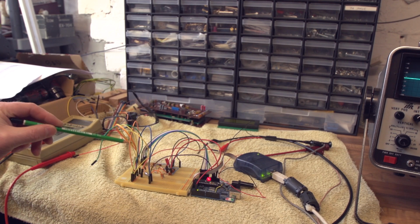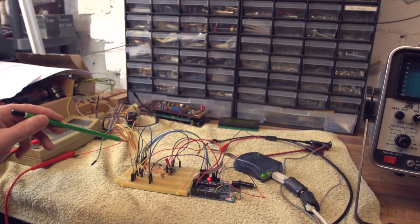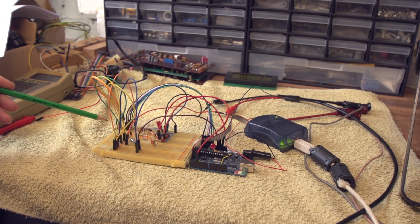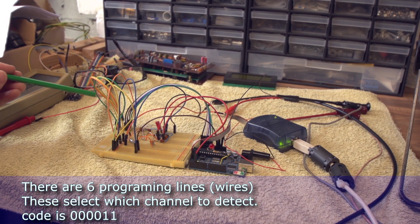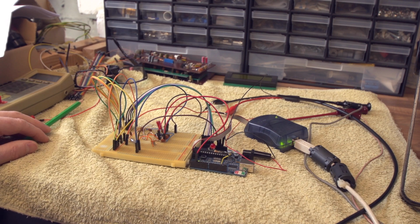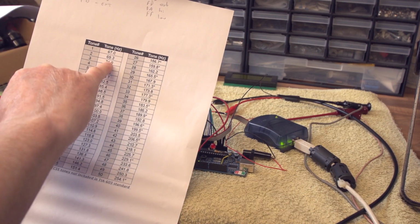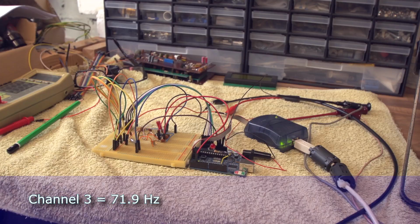I'll change the detection frequency, by changing the binary code, and I'll be back in just a second to do that. Okay, so just like magic, I've changed the binary code driving the firmware, and we're now presenting it with channel 3, or binary code 3. So it's like 11000 going from right to left. So it's channel 3. Now if you look at the chart for channel 3, we should be getting detection at 71.9 Hertz. Okay, 71.9. So let's try that.